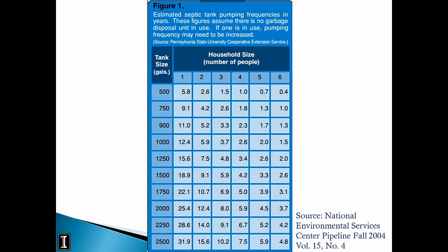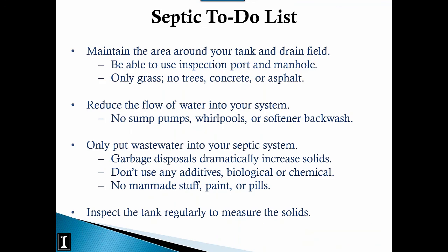And if you have a garbage disposal, I would cut that in half. And I'd also have it inspected probably in the middle of that, just to be sure that there aren't more solids in there than you think. And again, it depends on your use. If you're cooking at home every day and you're using a lot of vegetables and everything else, then maybe even less time if, again, you have a garbage disposal. But this is a guideline that gives you an idea of how fast your tank would typically fill up with solids. And so it's just something you can use.